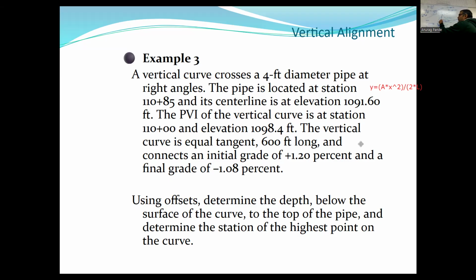Okay, so that's good. So I got one point. I need to figure out this point. I know the offset. All I need is, if I can somehow find the elevation of this point, I can get the elevation of this point by subtracting 2.82 feet. Now, how do I get the elevation of this point? That's pretty easy as well, because I know this is a point on the initial tangent whose slope I know is 1.2%. So if I know the elevation here, I can add that this is 85 feet, and I'm having a slope of 1.2%. So I can find the vertical elevation gain from here to here.